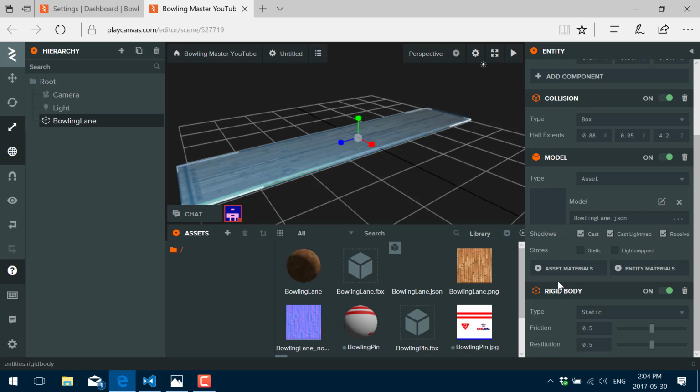But as it stands for this particular simulation, ironically enough, the settings that we get by default almost perfectly match what we want it to be. So we'll stick with that. You can play around with the physics to your heart's content. Just make sure that it's static and make sure that your shape is done and set to be basically the same shapes as your underlying polygonal mesh.